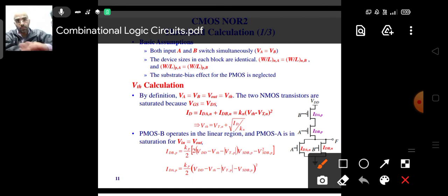Okay, the input is becoming VTH at that instant. So VGS is equal to VTH. And the output, which is drain to source, is also at VTH. Okay, we want to find this VTH voltage. So at this point, your input and output both are equal. So Vout is also at VTH, so VDS will also be equal to VTH.